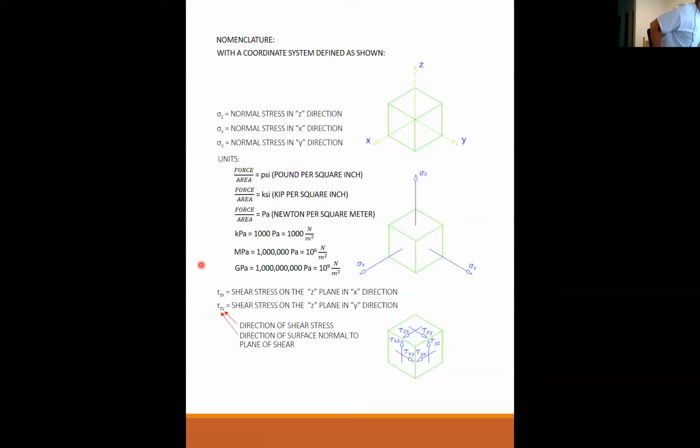Again, I mentioned this a couple lectures ago. My recommendation is when you are doing problems in the SI system, convert from the very beginning everything to newtons and meters squared. Then just keep track of all these multiples, 10 to the 9th, 10 to the 18th, whatever it may be, but keep your units straight.